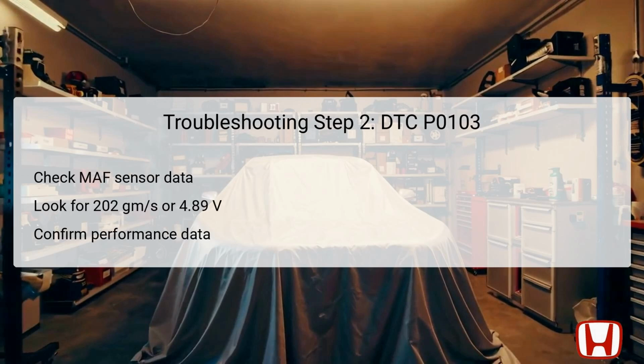After recording the freeze data, the next step is to check the MAF sensor data using the Honda Diagnostic System, HDS. This tool will display the MAF sensor readings in grams per second, gm/s, or voltage, V. Ideally, you should look for a reading of about 202 gm/s, or a voltage of 4.89 V. If these values are indicated, it points toward a potential issue within the circuit. This data is crucial as it displays whether the sensor is functioning at expected levels or if high voltage readings are genuinely present.